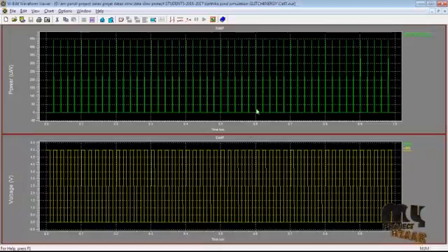The overall glitches will be reduced in the output waveform voltage, and it also improves the conversion rate, time is reduced, and overall area is reduced. So using binary weighted current steering digital to analog conversion has a lot of advantages over the conventional digital to analog conversion.